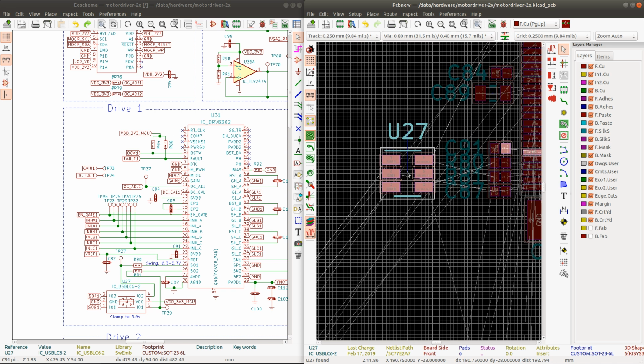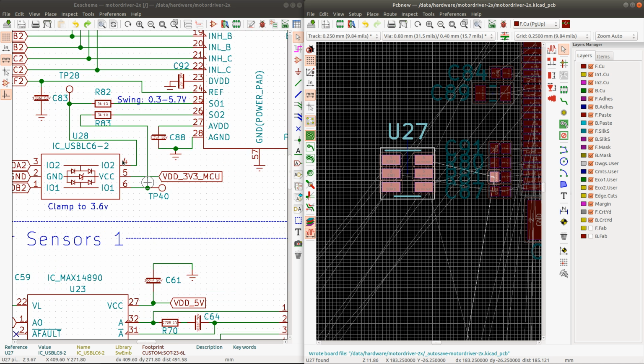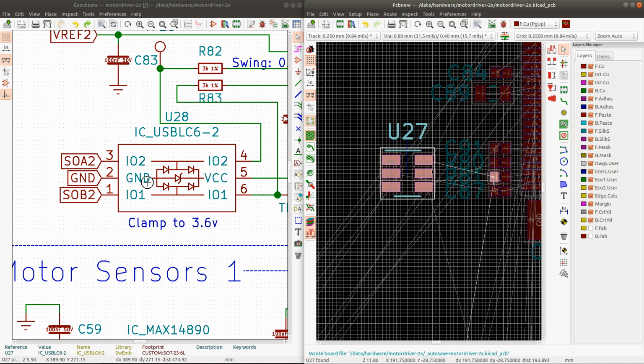So this needs to be rewired, because the footprint of this diode doesn't really fit together with the layout of this circuit. So what I have to do is just reconnect these pins so that I swap pin 3 and 1 and pin 4 and 6. And then I'll have them in nice straight lines, just going straight from the resistors to the diode and then farther out.